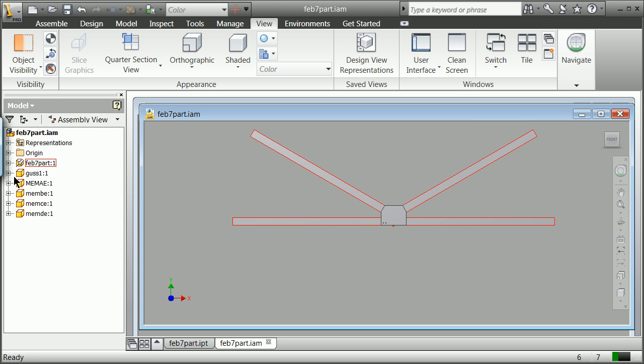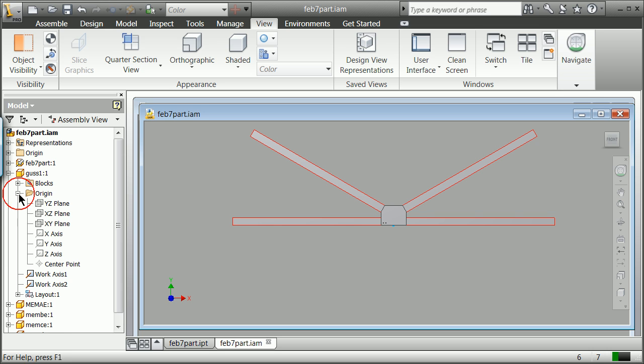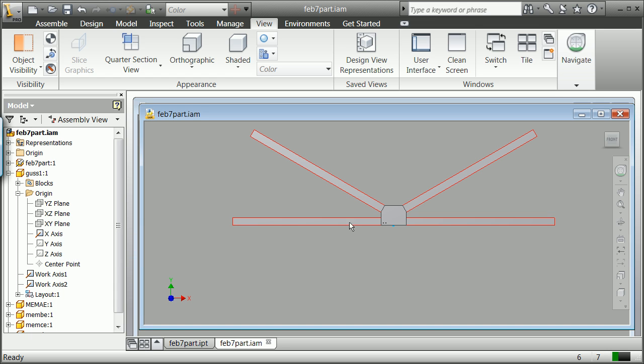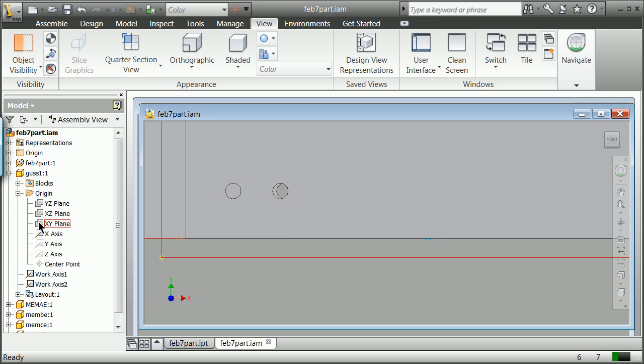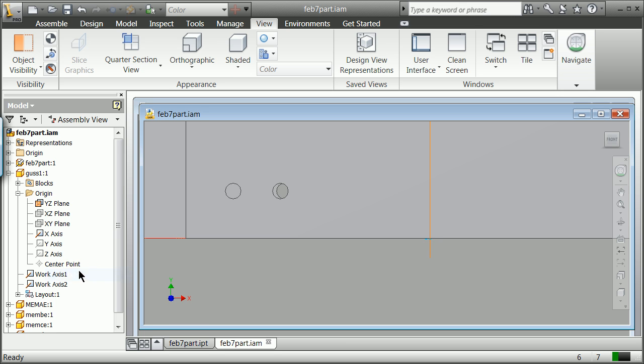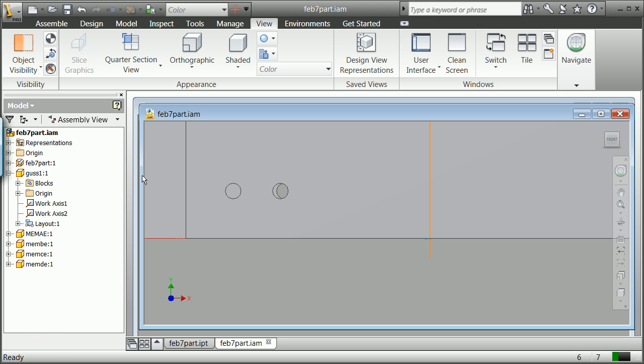And you realize there are a couple of views. I'm in the assembly view here, and I show you the gusset plate, and it's got some information here. You're going to see that you can turn the visibility on, for instance, on that particular point, or on right-click, turn the visibility on that plane. That is in the assembly view.